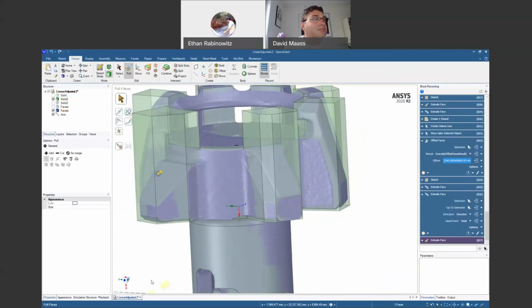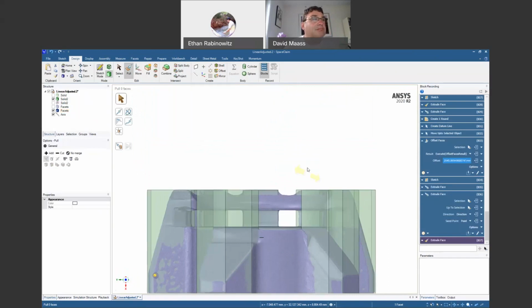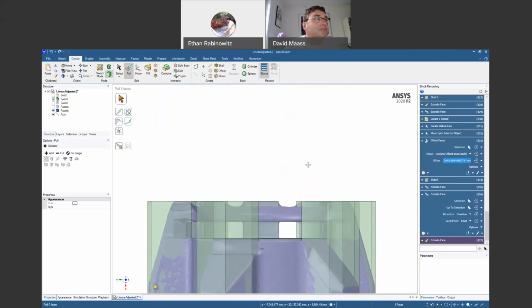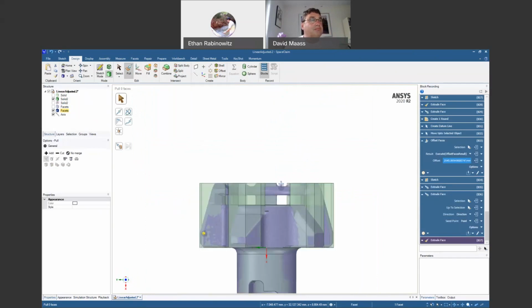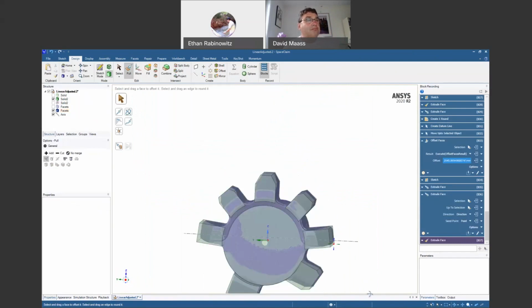Let's rotate it like this. Sometimes I actually just like to use the frame of the screen to help me with things. So if I click on this button, I'm squared up to our XY. And then if I bring this down here and put this edge right there, I can see that that's at a different height. So I'm just going to assume that these are different and we'll just cut them individually.